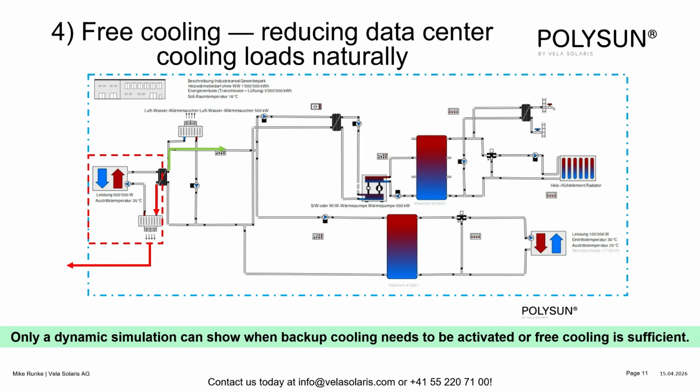Hydrothermal networks transport the cold water from the natural sources directly into the cooling circuits of data centers. The heat absorbed in that process is then increased to a usable level by heat pumps, making data center heat recovery both the cooling solution and the energy source simultaneously. So the result: the data center is cooled and simultaneously I provide heating for the city or the location.